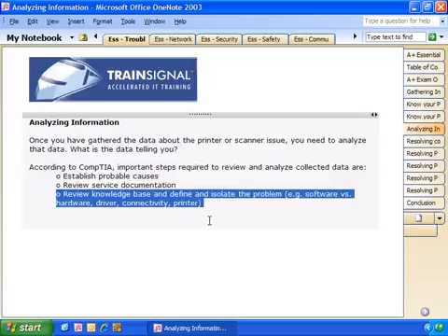I had a situation where we had a large printer and it was working fine, and then one day it just started jamming. And we tried everything, took it apart. We had a certified technician come out. He replaced the parts. We replaced the toner cartridge. All these things we went through, and finally it was determined that the cause of the jams was that the company that we got our forms from, the roll that the forms were being taken from had gotten very small, and what the effect was the forms had a bend to them. The forms were kind of arched, and this arch, as the form went into the printer and went through the different rollers and stuff, at one point the arch in the paper was causing the form to jam right there.